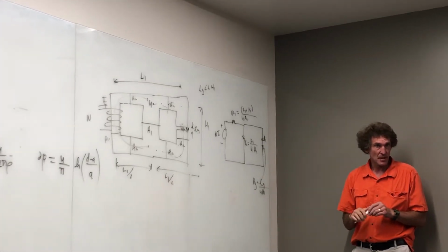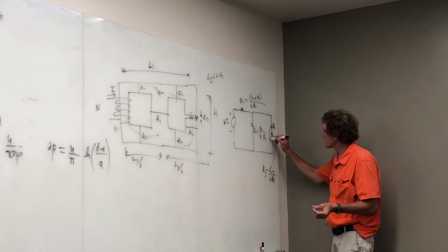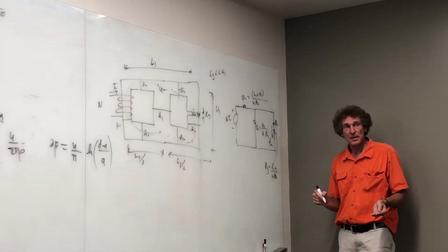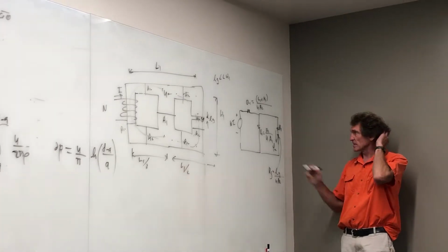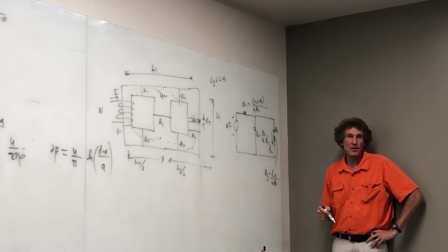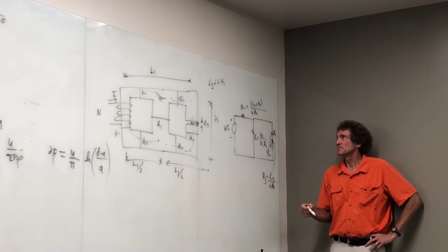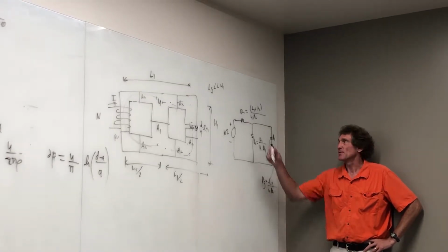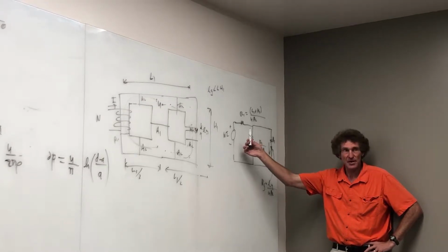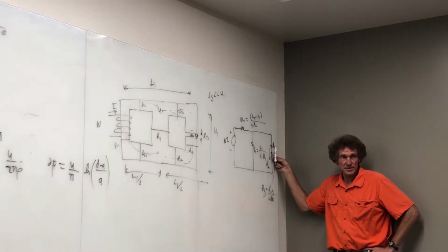Everybody see this? Now, if I wanted the magnetic flux in the gap, that's like current, isn't it, class? So how would you get the current there if this was the electrical analog? Talk me through it. There's a couple of ways. You could just do a Norton equivalent, right? And put Ni divided by R1, get a current source, and then put R1 in parallel, and then you have 3 parallel resistances, right?